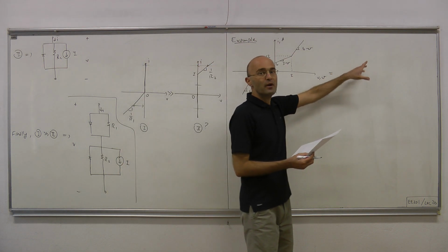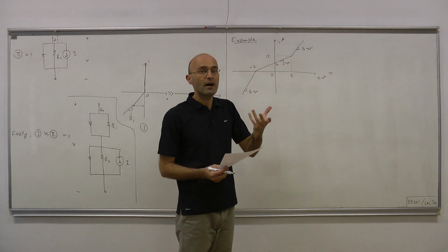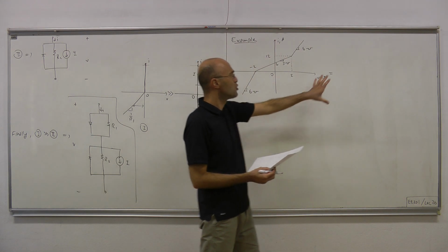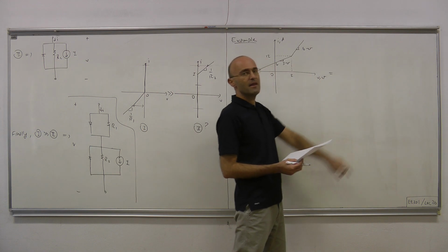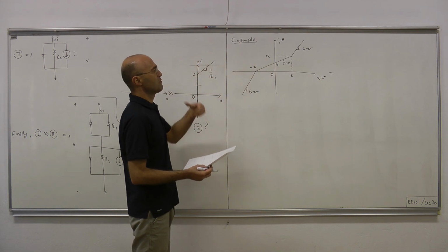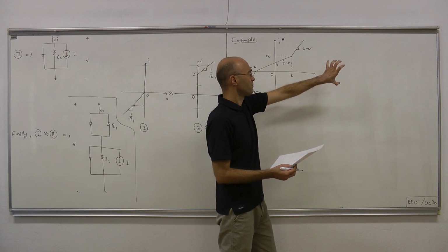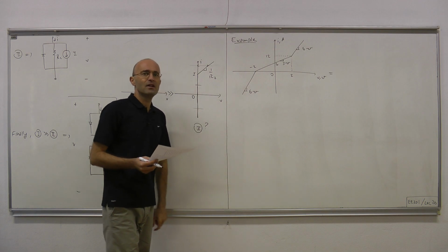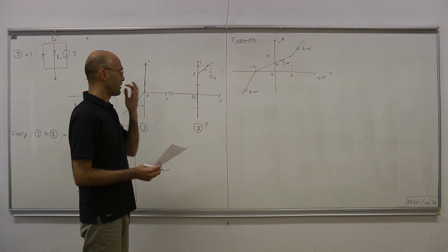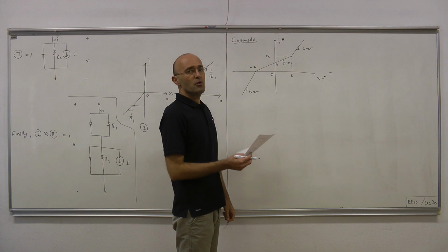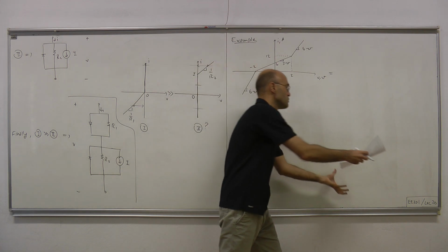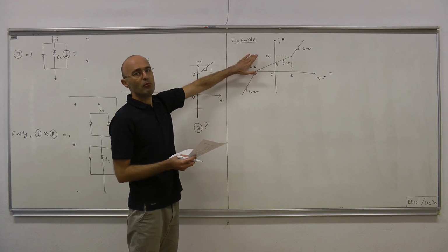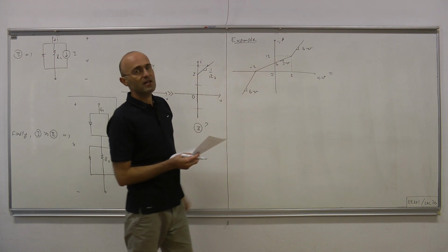Then try to recognize those simpler curves, by which I mean whether you know a one port that will generate the particular IV characteristics. If you don't recognize those particular subcurves, you decompose them further until at some point you recognize the one port, and then once everything is recognized, you construct from bottom to top the one port which would in turn generate this IV characteristics.